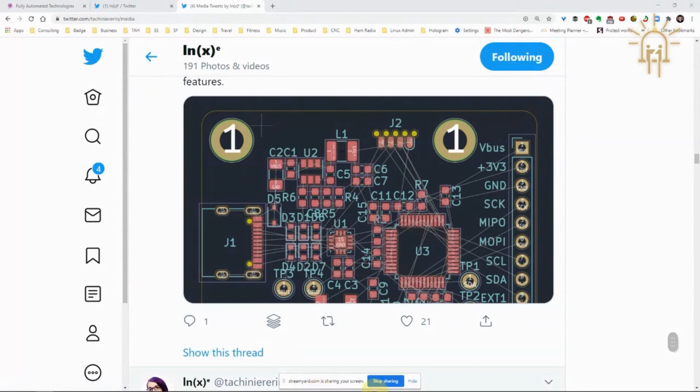And then the STM32 U3 does the whole higher level protocol handling, and which then talks to the host, to the power supply, and asks it for the right voltage. Got it. That's great. And then you're switching to STM32 as well, so that's kind of interesting. Yeah, because it's much cheaper and also has USB integrated, so it's the best fit for that purpose. Got it. To be able to just plug in and go from there. Exactly.